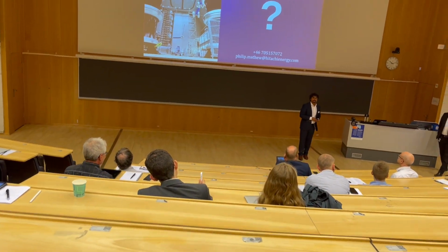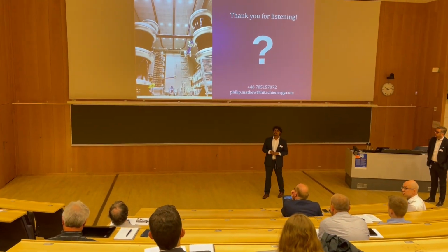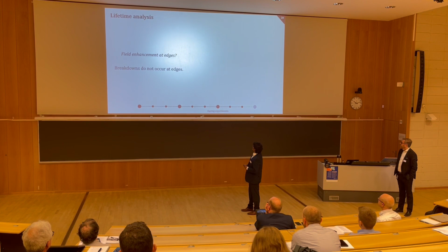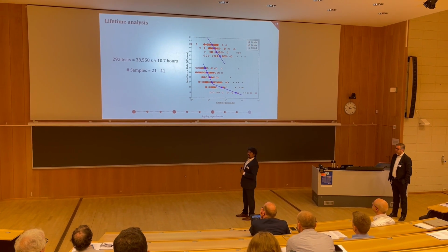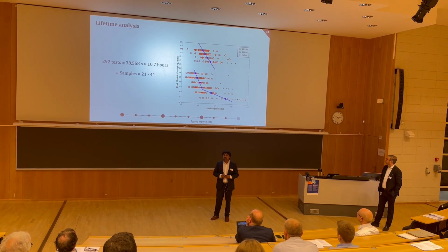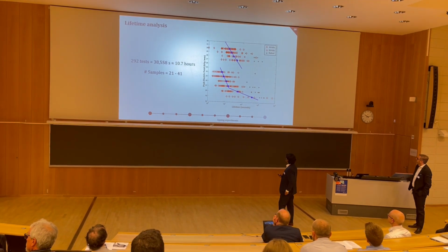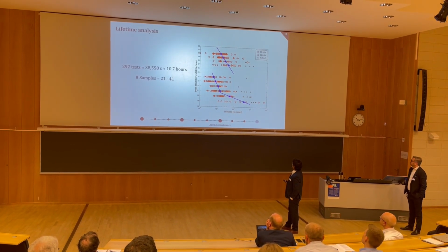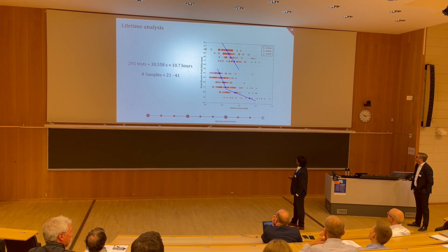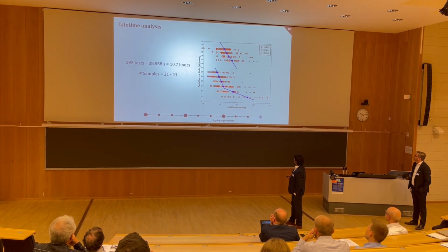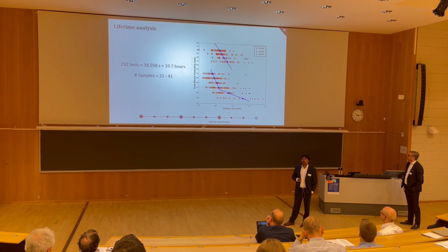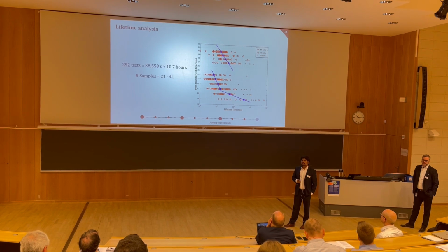Maybe you can show again the slide with all the measurement results. Yeah, that one. Are you really sure that for the 50 kilohertz results we have a change of the lifetime exponent? It's always difficult to handle experimental results, and what kind of distribution do you apply? Is it Weibull, normal, how do you evaluate the censored results and so on? Maybe it's only, again, one lifetime exponent.